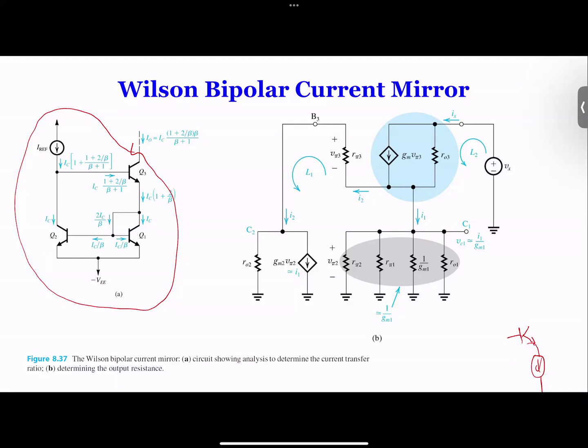Therefore, you have connected the base to this. Now you've got the top circuit. If we want to get the output resistance, you apply a voltage at the output, calculate the current, and use voltage divided by current to get the whole equivalent resistance. Apparently, this circuit becomes a little tricky because it's quite complex. We have to do some manipulation, mathematics, or node analysis.